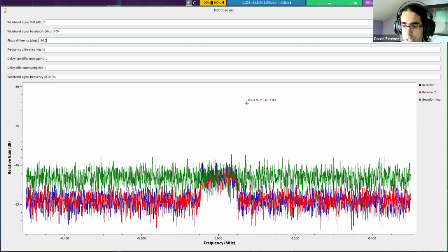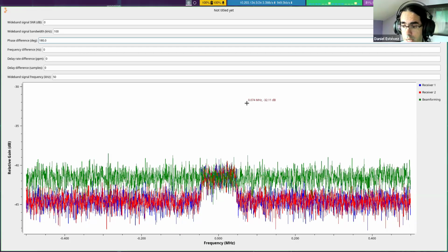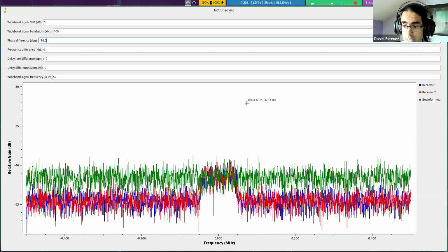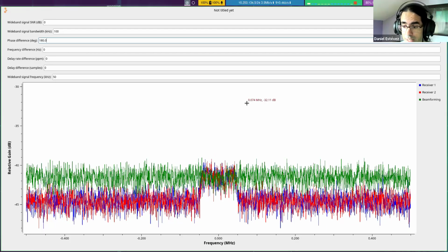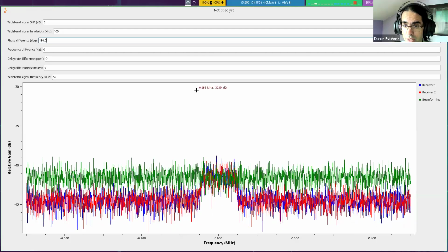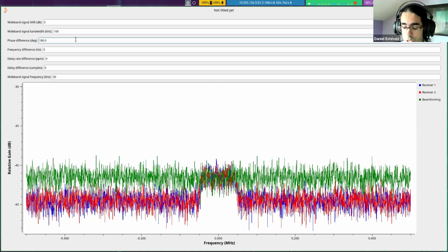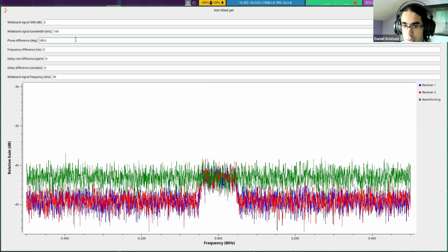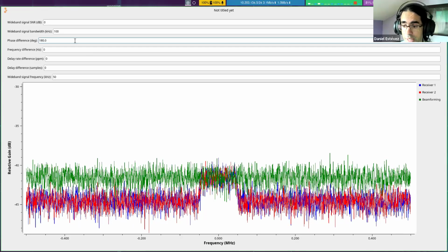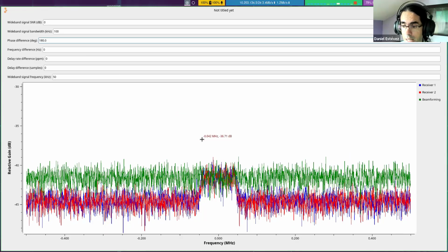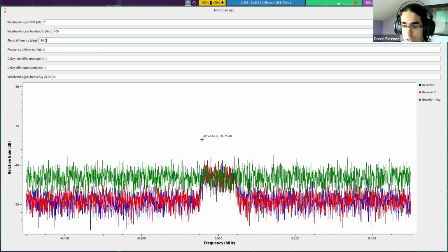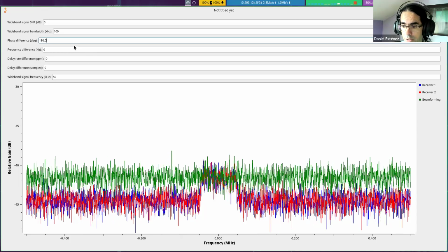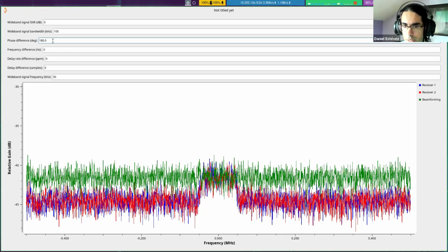But there is a situation in which this is useful, which is perhaps we have an interference, and the thing we want to do is to remove that interference. So we can play this trick. We can use the signal from multiple antennas to cancel each other out and remove the interference, often completely, like in this example. And this is called null forming. So that's also interesting. It's a method for interference cancellation.